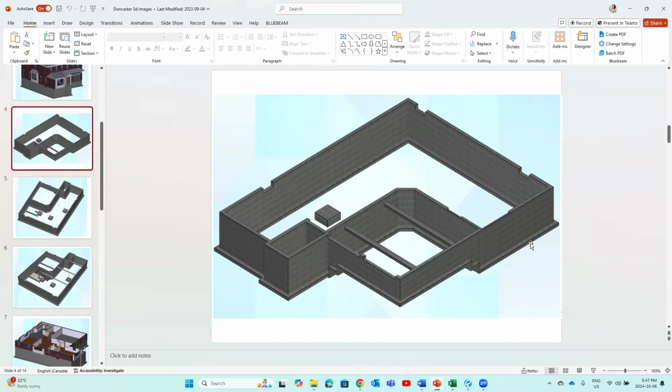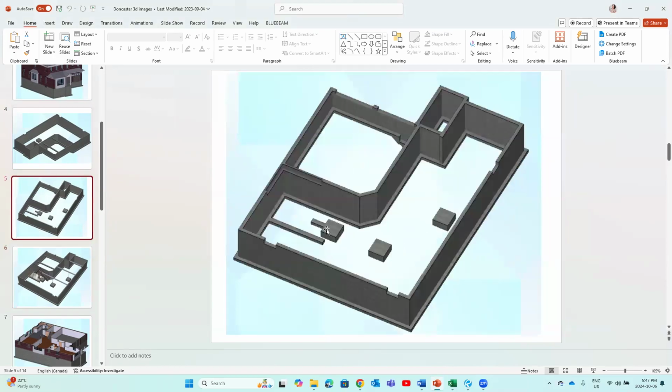For the regular footing, we know the depth of the foundation wall footing is 155, and the depth of the partition wall footing is 150. So both of them are smaller than 200 millimeters. That means we are going to measure the formwork for the foundation wall footings by the lengths.